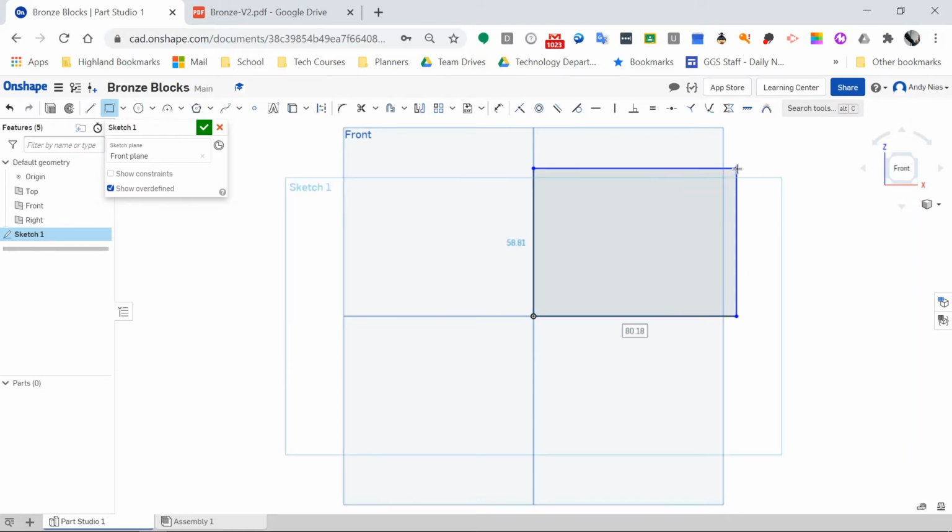I've now got an option to put a size in. There's a little white box highlighted. If I type 6 and 0, don't press backspace or anything else, just literally type 6 and 0, hit enter. That puts my dimension on that width. Now it's jumped to the other box, and I want to put 5, 0 and enter.